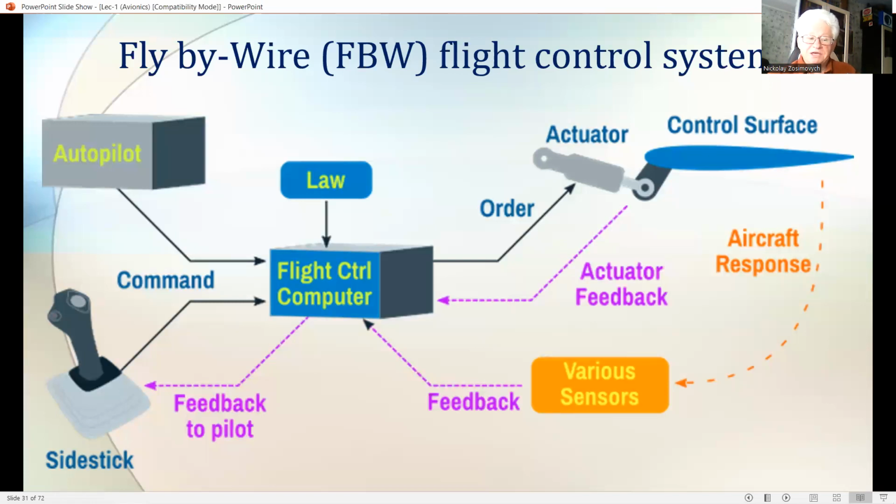It does this by providing continuous automatic stabilization of the aircraft by computer control of the control surfaces from appropriate motion sensors. The system can be designed to give the pilot a manoeuvre command control, which provides excellent control and handling characteristics across the flight envelope.